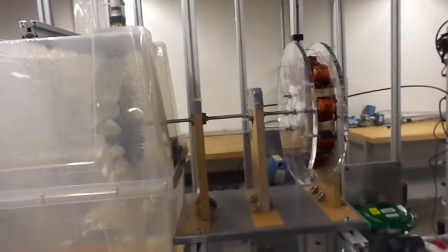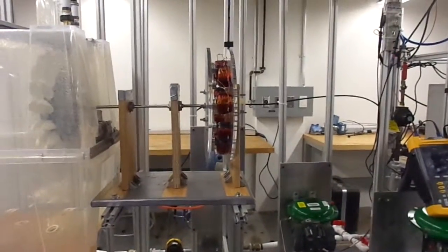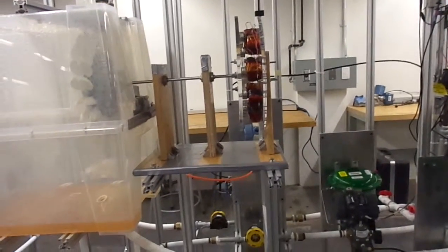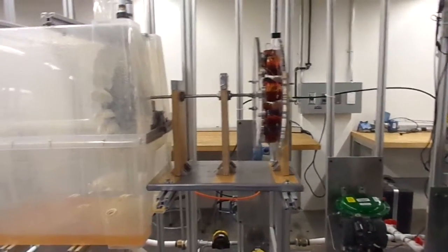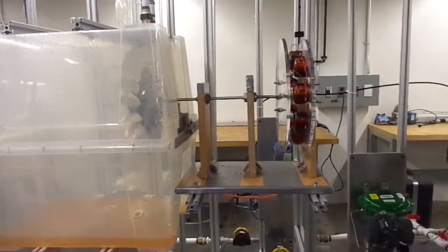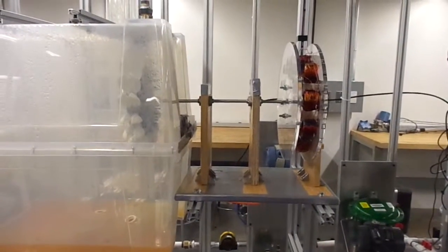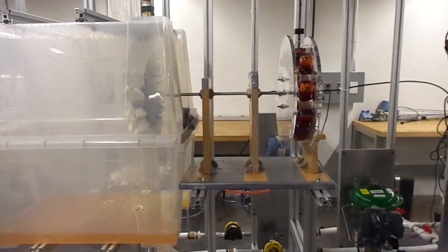When the generator runs with no load, it goes up to 48 Hertz, which, if you convert it to RPM, is close to 3500 RPM. Once the load is put, frequency drops to 40, 42. Sometimes the max we get is 42. And the voltage will drop based on the load. But without a load, the generator is up and running.